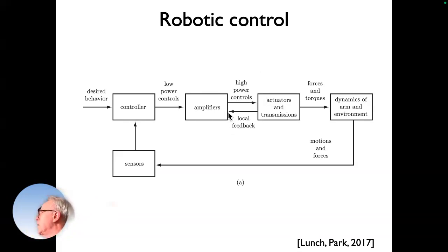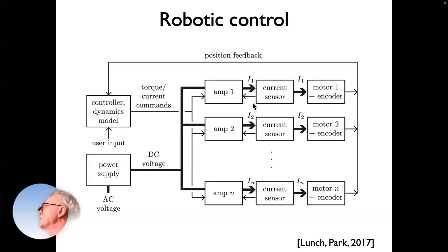Other than that, it's just the same diagram. You do have a control loop where you're also sensing the electrical current in the motor, and that current reflects how much it took up your command and actually generated the physical force or torque that you wanted.